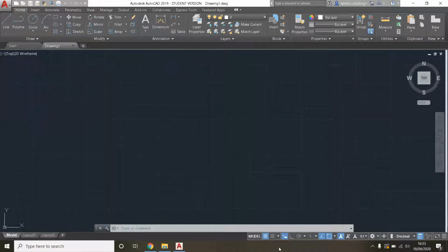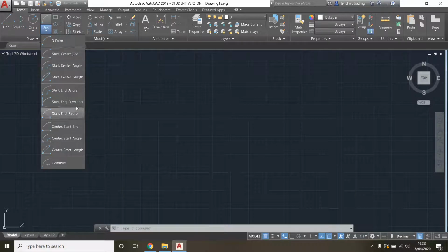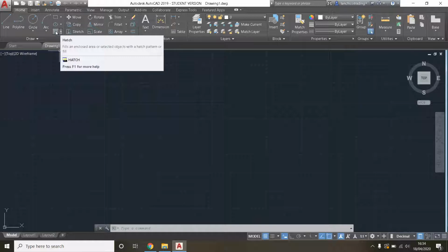Okay, here we are. We are now in session 2. In the first session, we checked our drawing tools. We looked at the line, the difference between a line and polyline, and we also investigated different types of circles. We played around with the arc, as I said. My favorite is the start and direction arc. We will see more of it in action in the later sessions. We drew using our rectangle tool, we drew an ellipse, and we started hatching some stuff.